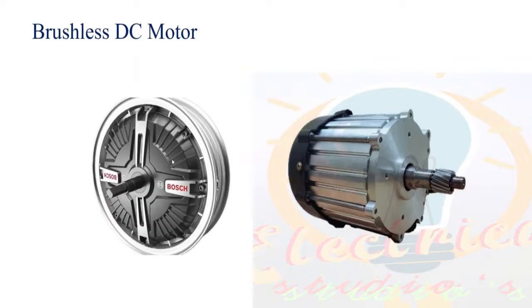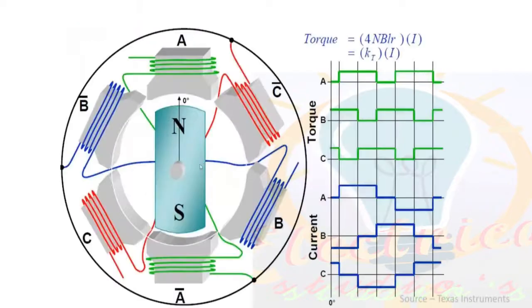But depending upon your requirements, if your power capacity is low, then you can choose these hub motors. But as I told you, BLDC motors operate with 6-step control, and because of that you generate a lot of torque ripple, which makes it not a suitable candidate for high speed applications. So when you have a demanding, higher power application, you should go for PMSM compared to BLDC. If you want a magnet based motor and your application is high speed, then people go for PMSM, right? Compared to a BLDC, because the torque ripple issues can be avoided in the PMSM.